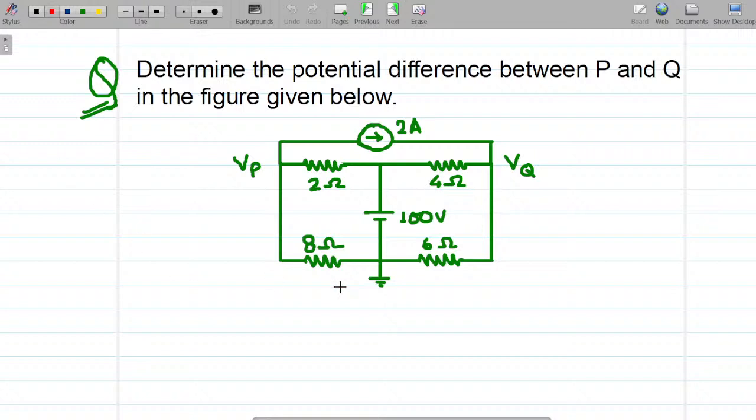Now, tell me, I'm traveling from this point to every point in this network. Tell me, would this be a node? See, whenever you encounter any element which is supposed to change the potential of this point, this was a conducting wire, and now you encounter an 8 ohm resistor. So there will be a change in potential. So yes, this is a node, right? But tell me, have I not defined this node as of now? See, this is already defined. How is it defined? Because this is at potential P. This is node VP. We have already given it a name, haven't we?